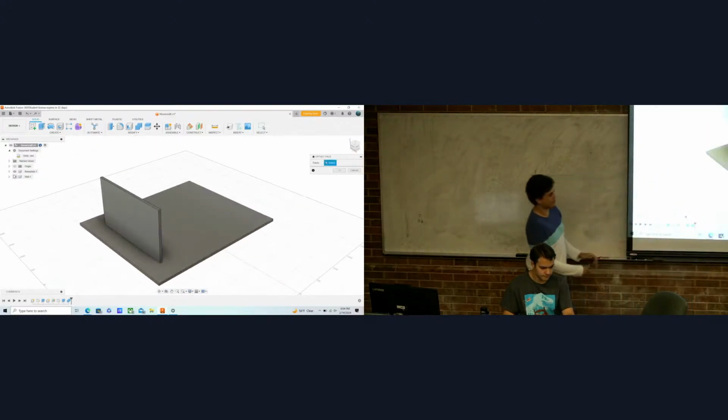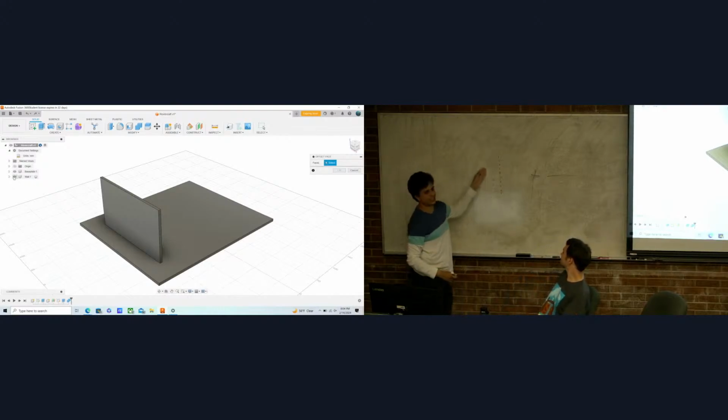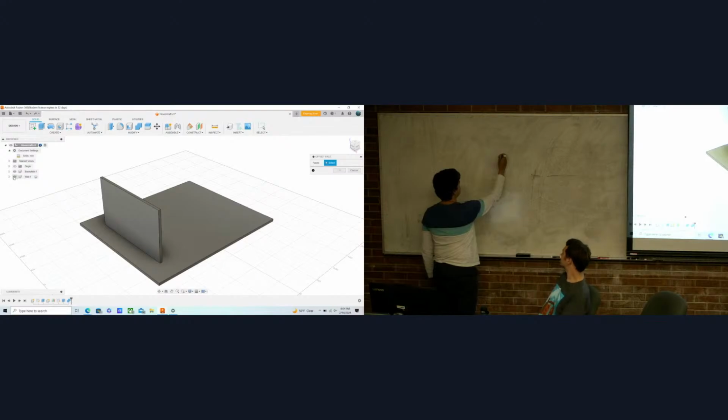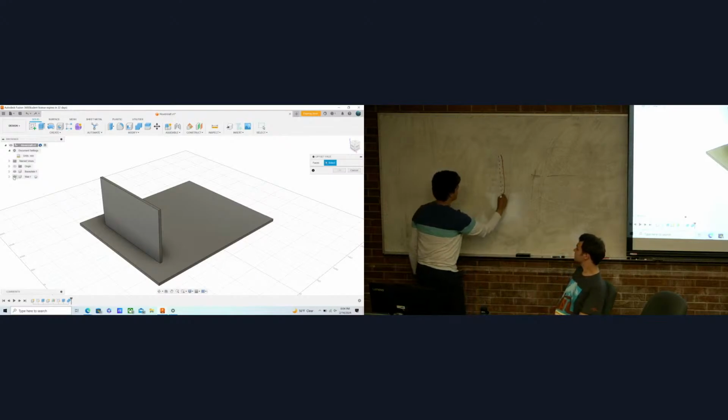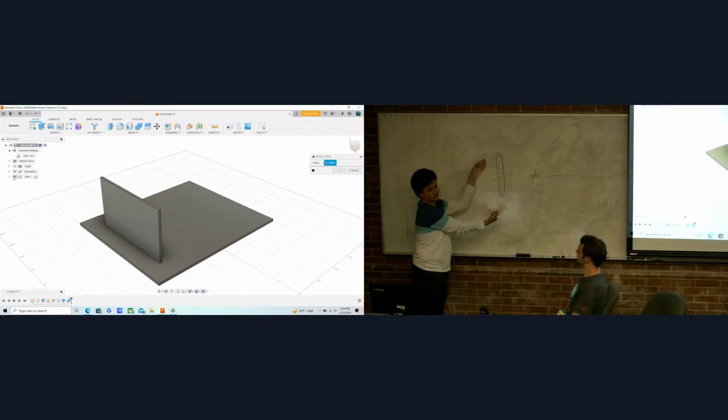And that's not real life, right? So in CAD, if you imagine that this dotted line is the imaginary line that CAD gives you, if I were to 3D print this line, when we actually have material, there's going to be material that looks like this. It'll be as small as the 3D printer can make it, but it's going to be larger than the imaginary line that CAD is giving us, right?